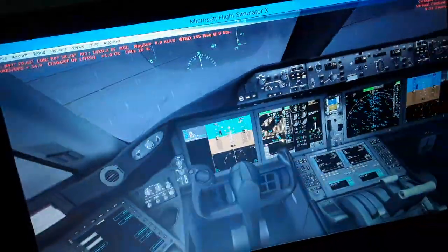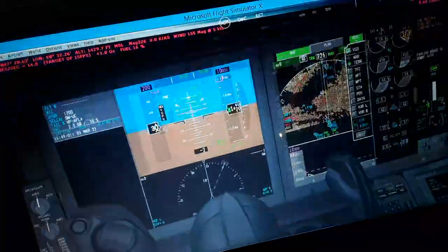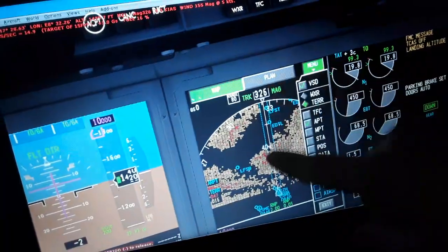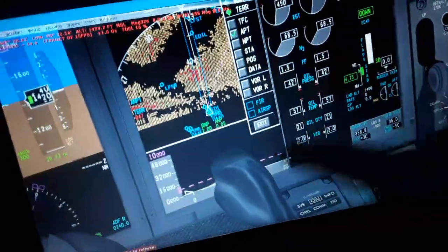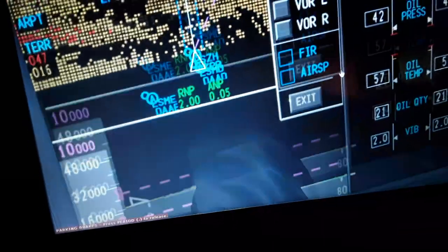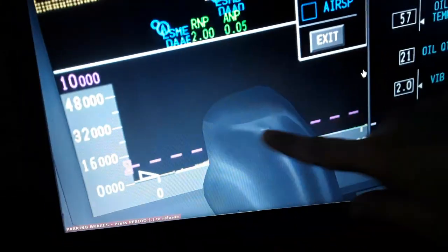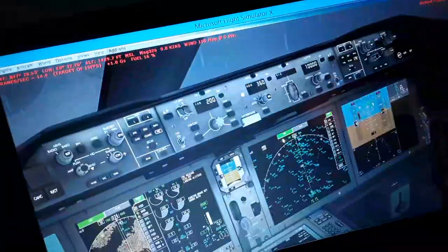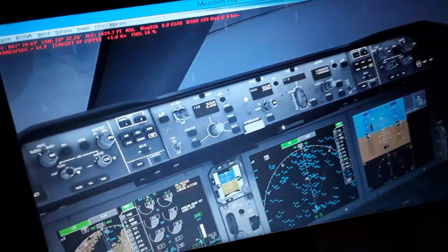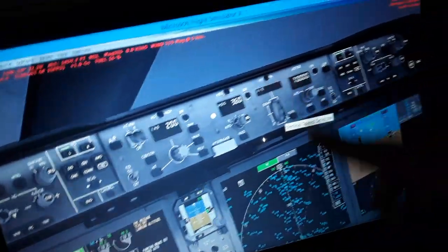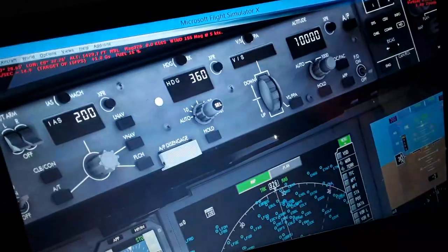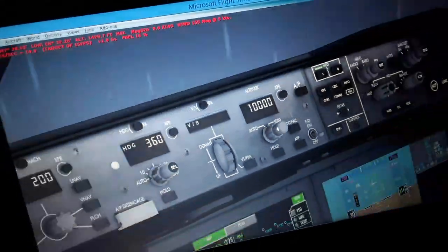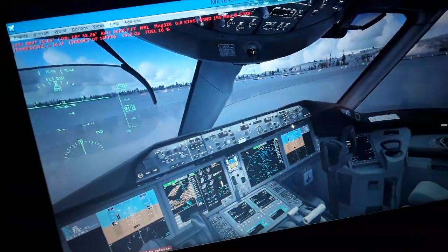So we have also, you can see how far above the ground the aircraft will be flying, the terrain. Here in the navigation display, the terrain map, the airports, magnetic heading over here. How far above we will be flying, we will select the altitude later. Now we have 10,000 feet here, this line. It's also displayed here in the primary flight display, so these values, the purple, are from the autopilot flight director system panel, the airspeed, heading, vertical rate of climb, descent or flight path angle over here now is not selected, and the altitude also, altitude hold.